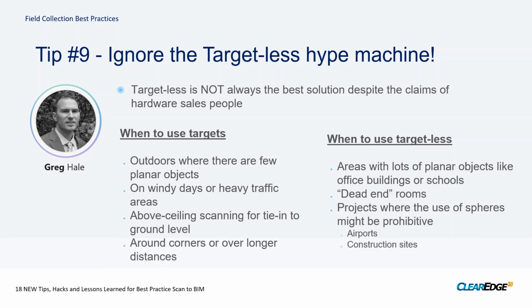So a lot of times we'll go through targeted registration through main corridors, we can tie it in. We can easily tie it into survey control. And then maybe 4, 5, 6 rooms kind of branching off of that can easily be done with a cloud-to-cloud registration. And we actually use them complementary to each other. But when we go through it, we plan on it, we make field notes. We understand that scanning is going to be a little bit different, trying to capture overlap instead of targets. So we do it within the plan to make sure that we're scanning appropriately when we do that.